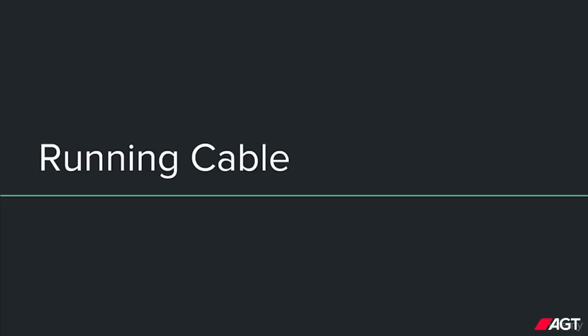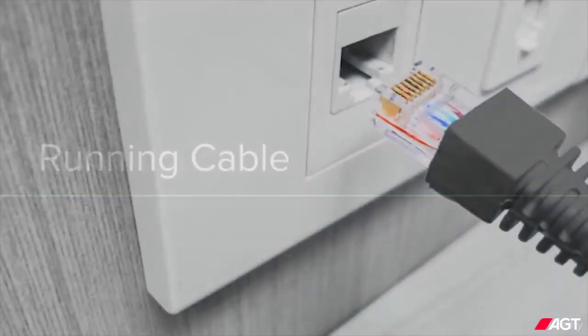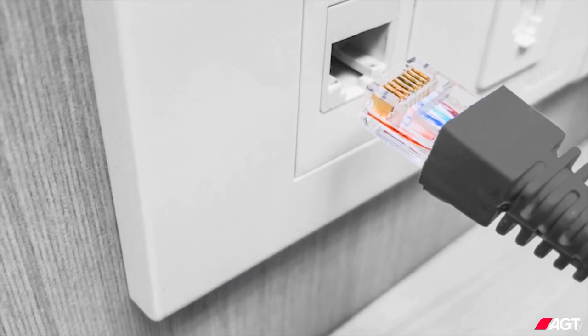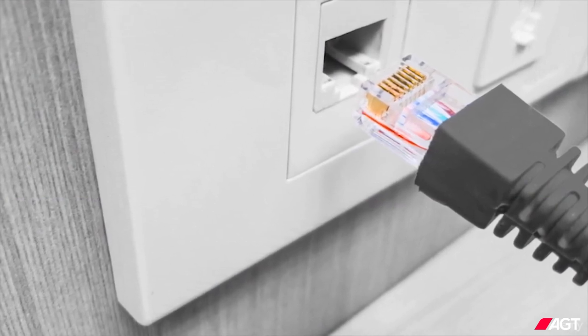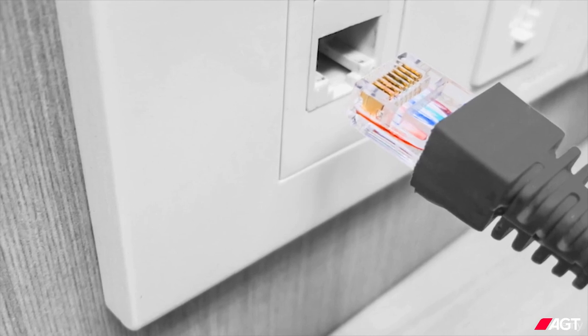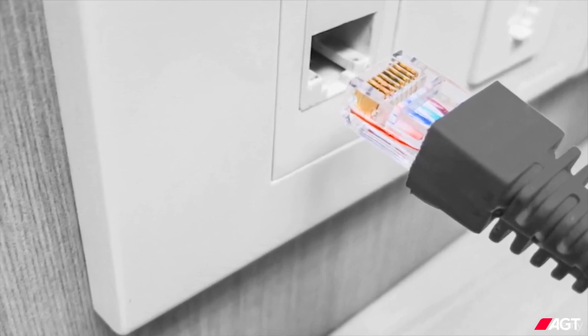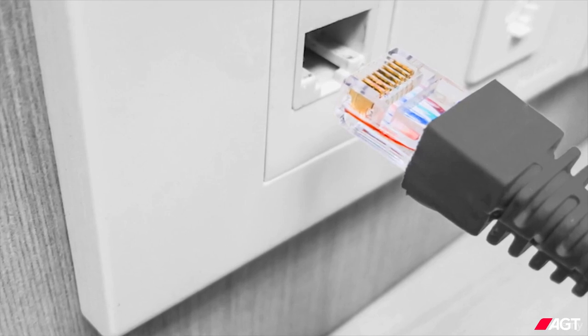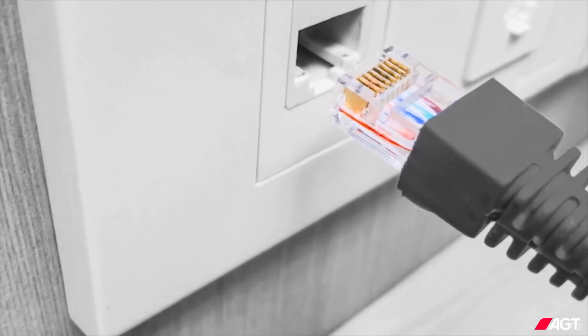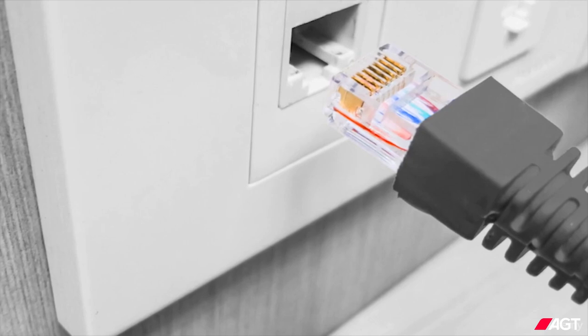Okay, so pretty much every cabling job you encounter is going to be different. Different building, different demands, etc. I've already gone through all the actual wiring specifics. The only thing left is actually running your cables. Again, this will depend on the setup you're cabling. For example, if you're simply installing a wall jack, you might create a female to male cable, plug it into a modem, run it through the walls, and install the plate with jack onto the wall. For installing plates into drywall, you also might need a small drywall saw. They're actually really handy for cutting precise shapes.